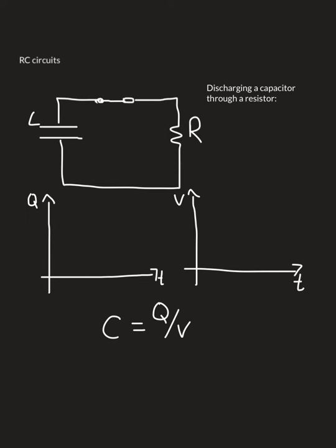As soon as the switch is closed, the charge on the capacitor is going to begin to flow. If we imagine the top plate is positive and the bottom plate is negative, then we visualize current as positive charges moving away from the positive plate and attracted toward the negative plate. So that would produce a downward current through my resistor. The capacitor begins fully charged and then discharges so that it asymptotically approaches zero. This is an exponential decrease.